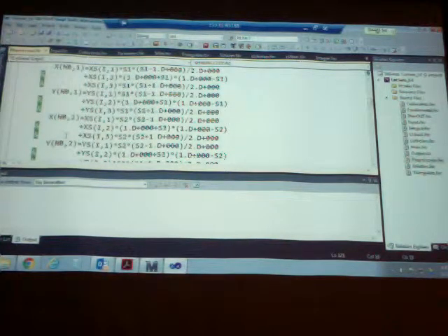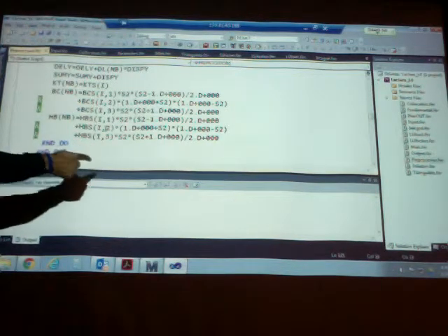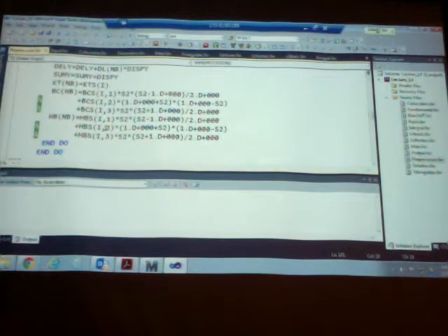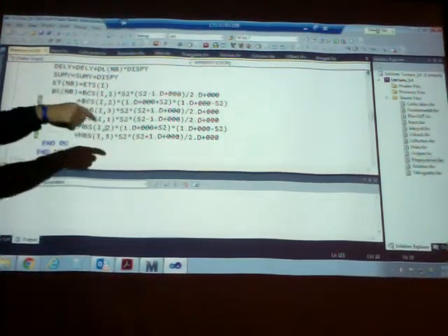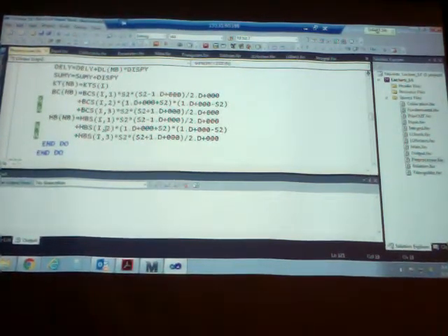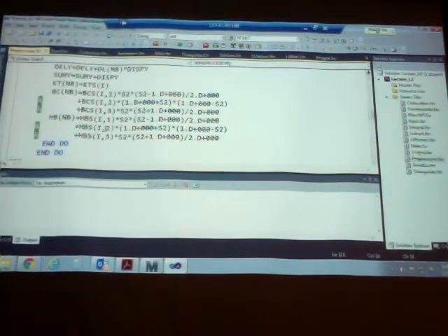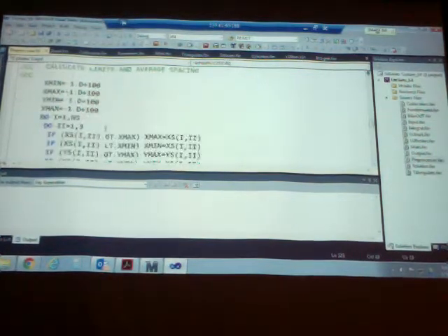After it does that, it also positions the boundary conditions on every spline, right? Because you can specify a spline that goes from here to here, where the temperature might go from 0 to 20 to 80. And it just does a quadratic spline distribution between 0, 20, and 80, and positions those values along all the boundary elements for the boundary condition and for H, which again, you don't have to worry about transforming, you just have to worry about the moment of implementing them in the system.